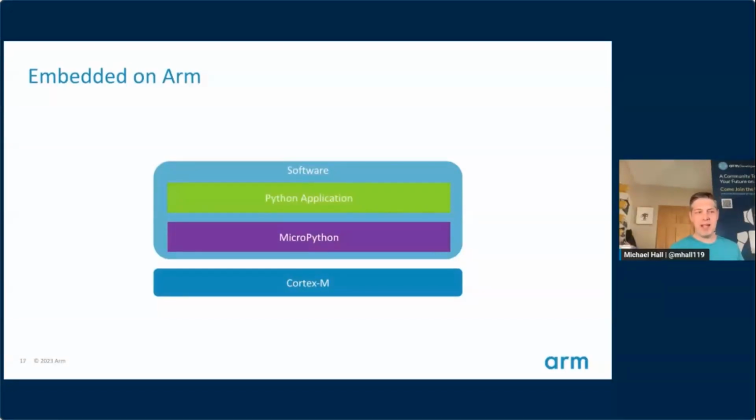You can actually run Python code on a lot of these devices. In that case, you're going to use MicroPython, which acts as the firmware. So MicroPython has that device-specific code, so it knows how to control the device. It's going to bring up a Python environment for your Python application to run in, and then that's all it's going to run. So MicroPython is not just an implementation of Python. It's its own RTOS and everything built into that. And it supports a wide range of hardware, including a bunch of the Cortex-M boards.